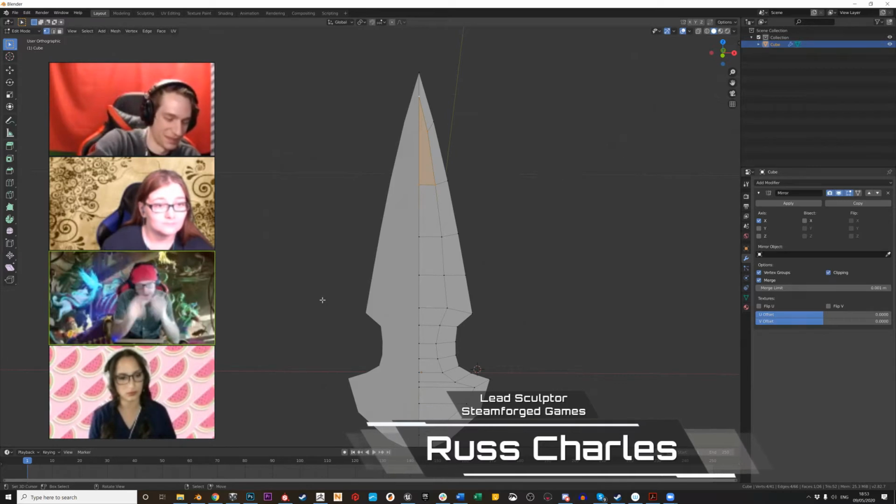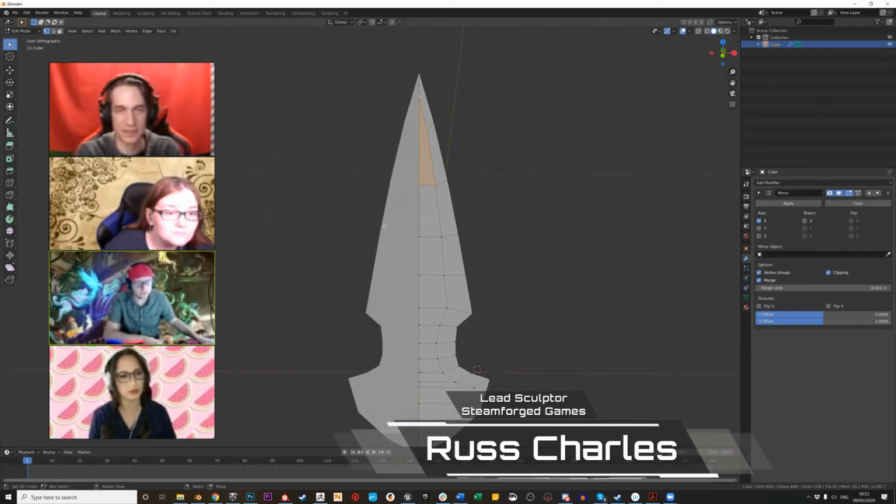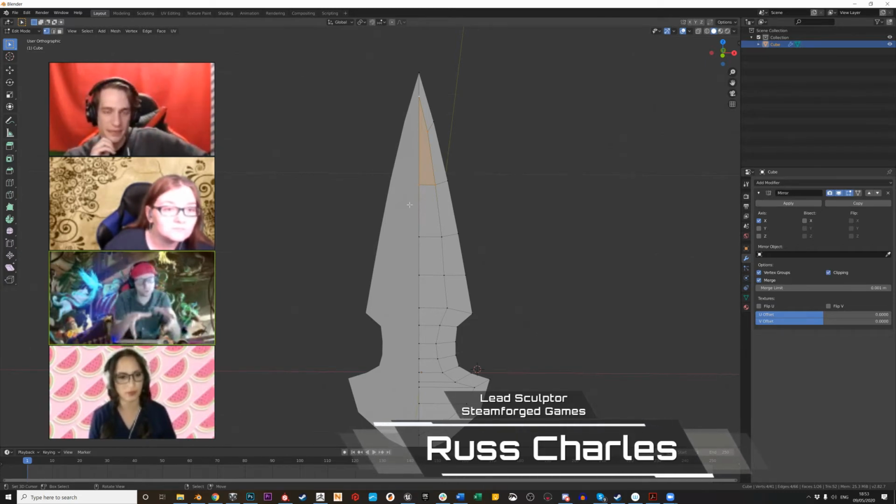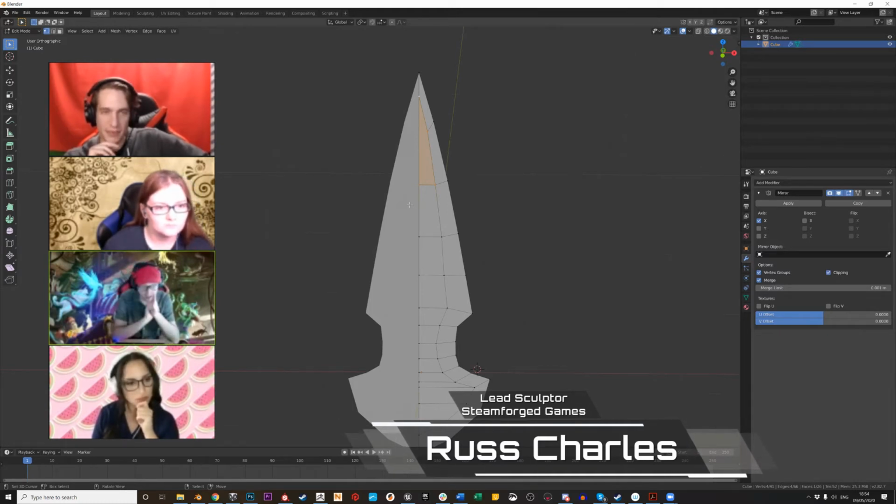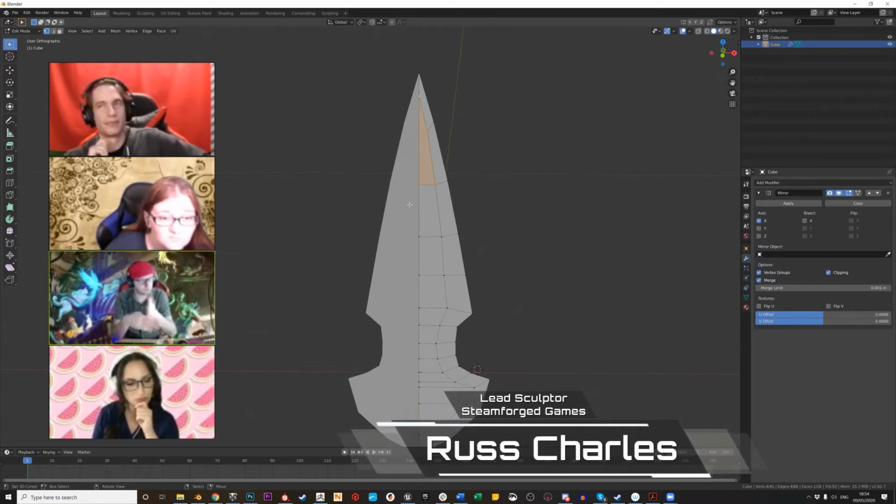Both of these things are actually handily really connected in how they interact. So, adding new vertices is as easy as adding an extra edge loop in. And the reason we work with four-sided shapes is because if you imagine you've got a square and you want to cut it through the middle from one side to the other, the line will go through the center and come out in a predictable direction. If you're trying to do that to a triangle or a pentagon or any other odd number of sides, the line cannot pass through the center and then pass out the edge of another line.